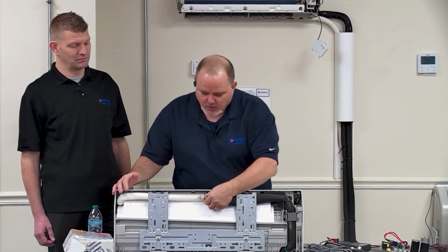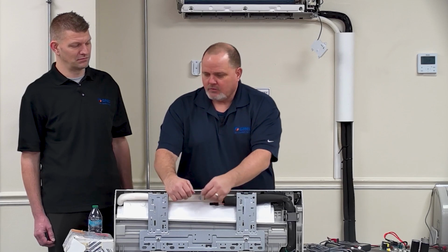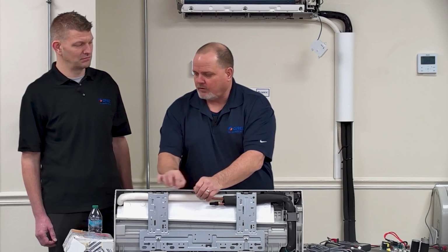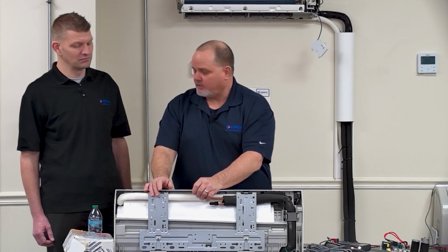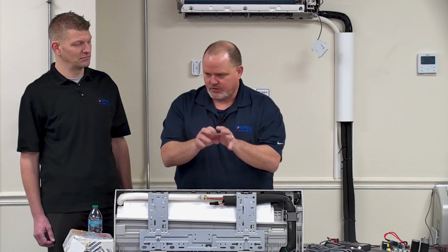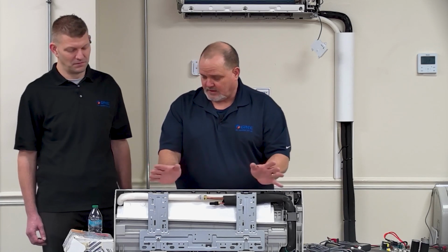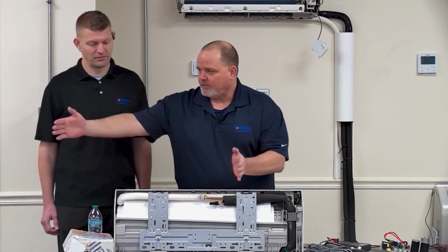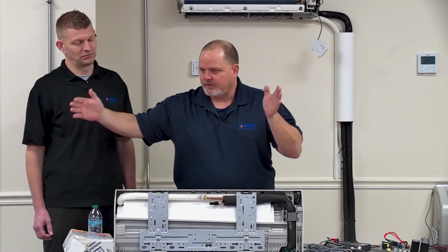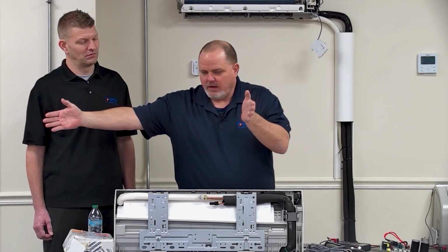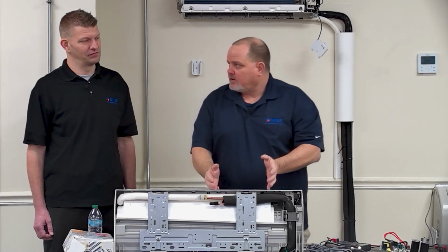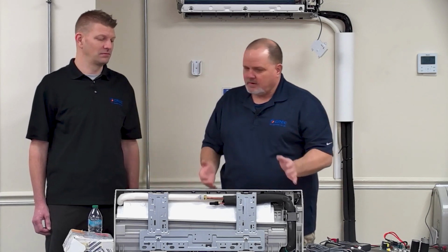So what you could do, if your refrigerant lines are coming up here, rig up some Schrader fittings that you can put on your pipes there, flow the nitrogen from here, and do your braze at the other end. You're going to be leaking here a little bit, but as long as you don't need a lot of nitrogen in the pipe, you just need enough nitrogen in there to displace the oxygen. Yep. That's it. So even if you're leaking a little bit, if your solder joint to a manifold or a wall or a Y branch is only 15 feet away and you've got your nitrogen flowing right there and you just go over to that 15 feet away and braze it, then you can take that and move it to the next head. And so every job is different.